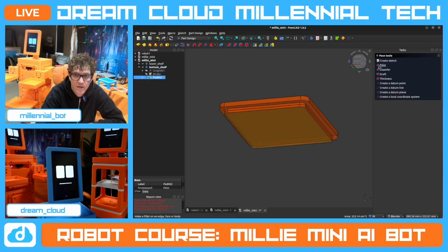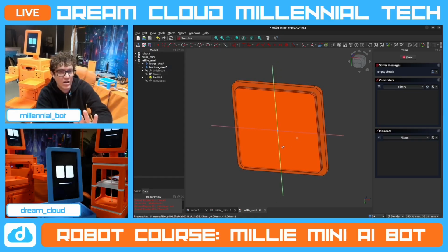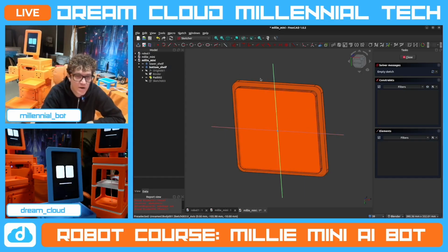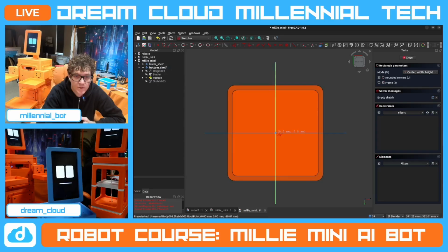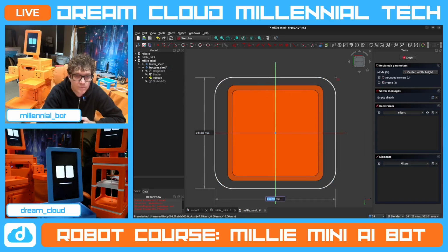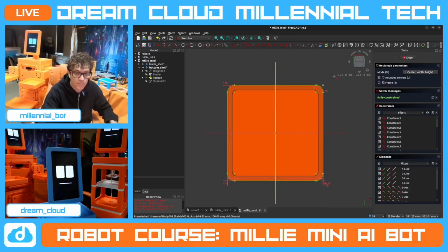We select that and then we create sketch. Again, we're back in the same thing where we're creating a sketch on the surface, on the bottom surface here. And what we're doing is we're actually creating a mirror copy of this larger 200 by 200 with 15 radius corners. And make sure we have center. And then we click, make sure it clicks on the very middle. Cool. So we're doing the same thing, 200, 200, 15, boom.